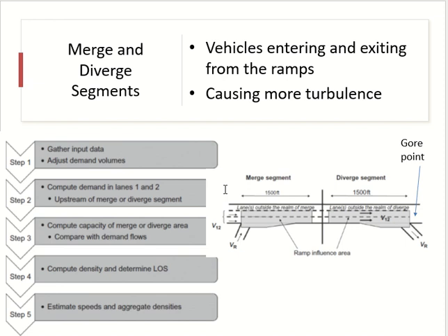Now this one is an exit ramp. So people who are going out from the ramp, will they affect the flow before or after? Before, when they are exiting. So before. Again, how much? 1000. Clear? And they are saying these two lanes are under the influence area. So 1500 feet in these two lanes is obviously having the influence of the ramp.